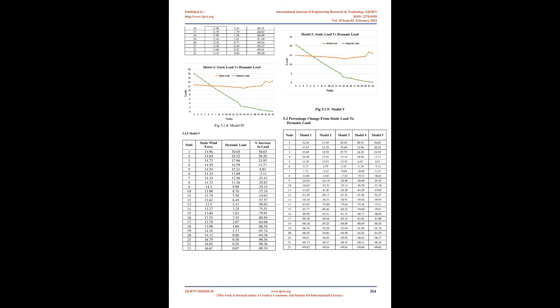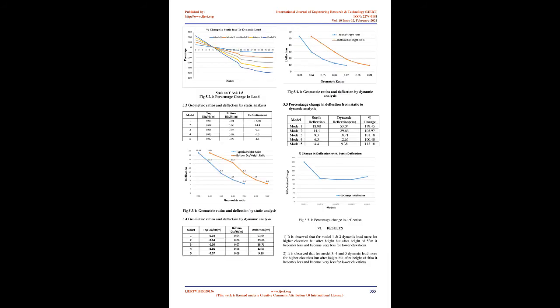Modeling and problem formulation. In the present study, a steel chimney of 80 m height subjected to the wind loads imposed due to the mean hourly wind speed of 39 m/sec in seismic zone 3 is considered for the analysis. A single flue of structural steel is provided to discharge the flue gases. The shell rests on an RCC mat foundation of circular shape.